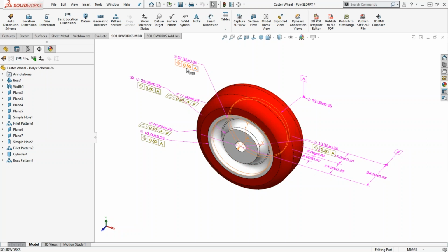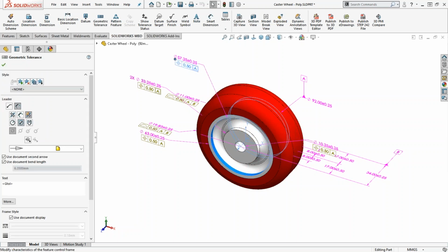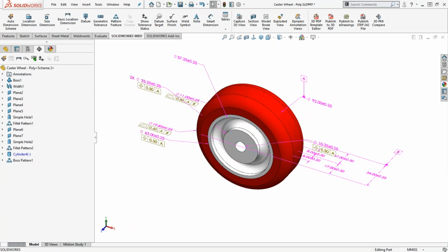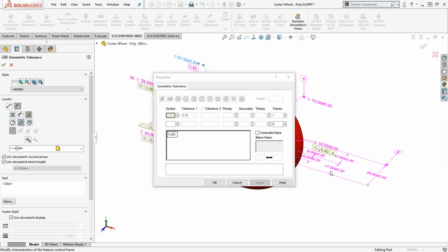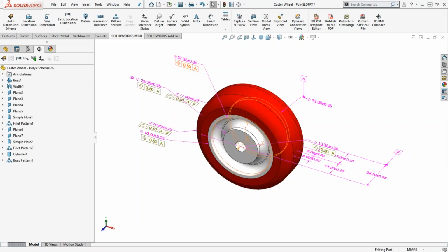So in this specific case, even if I go and select that tolerance for any one of these situations and delete it, for example, I can go back and add exactly the same tolerance as I did before, and it displays correctly. So I'm not sure exactly where the disparate references are for these guys, but in any case, whether they display in pink or brown, it seems to be fully defining the model regardless.